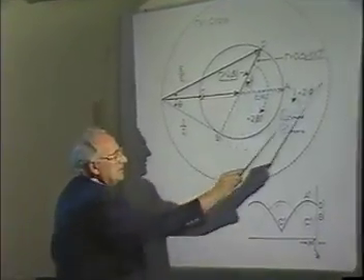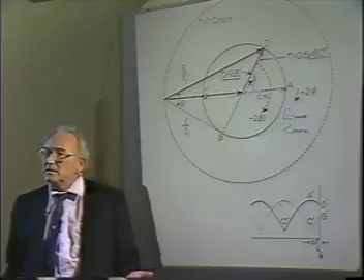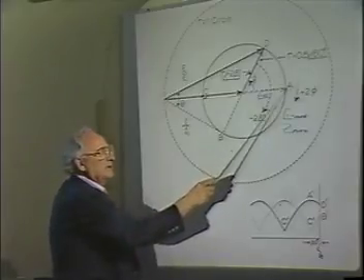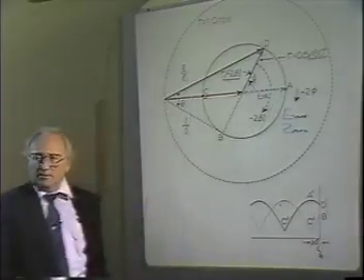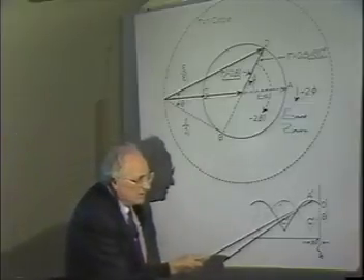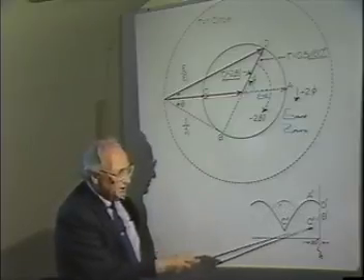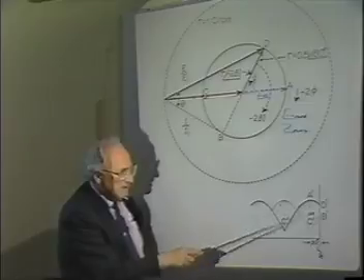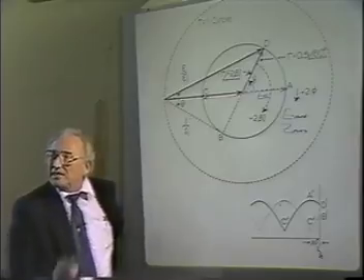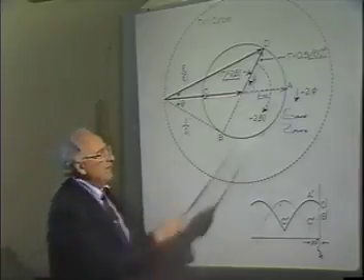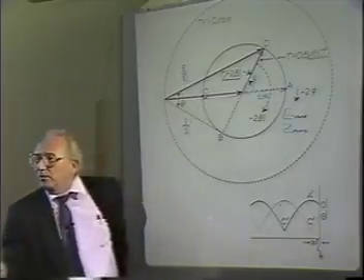Everything on the right-hand axis is a maximum if you look at this chart. If you looked at it in terms of admittance, it's still maximum admittance, because when the admittance is maximum, at the same point on the transmission line, the impedance is a minimum over on the other side. Look at this. If the impedance is maximum, what's the admittance? Follows the same curve as current, doesn't it? Maximum voltage, minimum current. Maximum impedance, minimum admittance. At the same point on the transmission line. Are they the same point on the transmission line? If you have Z max over here, what do you have over here? Z min. But those are the same point on the transmission line.